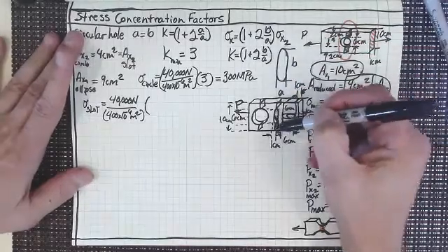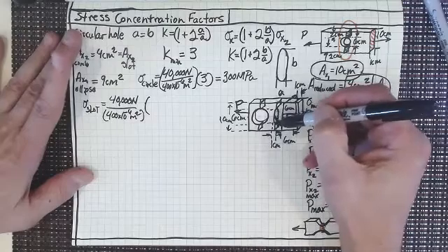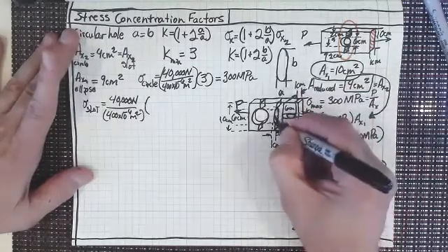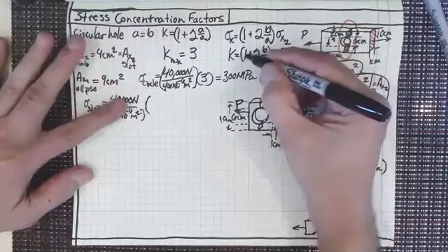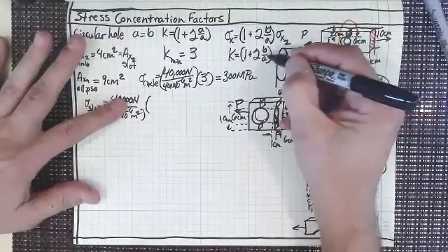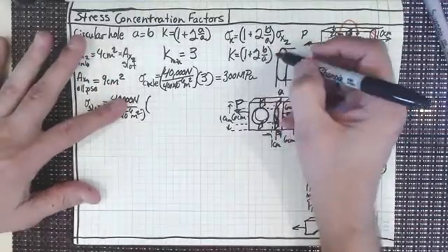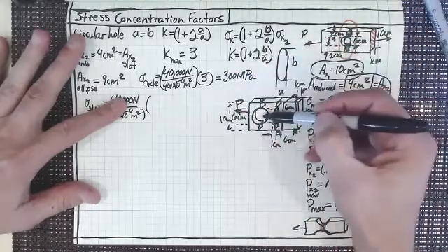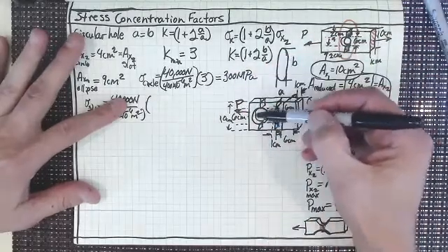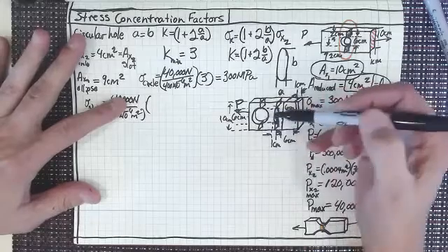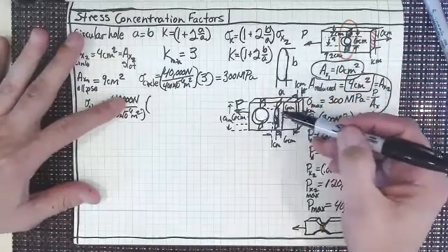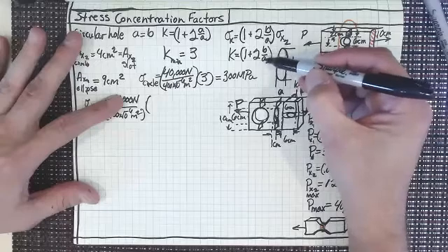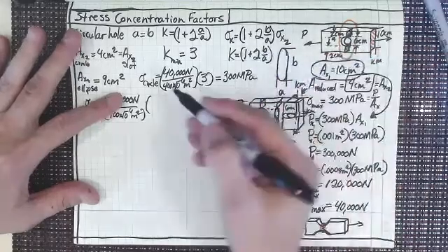You see what that electrical engineer has accidentally done? He's actually put a stress concentration factor of 6 plus 1, right? That's, oh no, actually 12 plus 1. So he has increased the stress concentration factor from 3. That's why the mechanical engineer actually put the circle in there in the first place. And instead, by cutting the slot in there, he has taken it from, this is 6, 2 times 6 is 12, plus 1, 13.